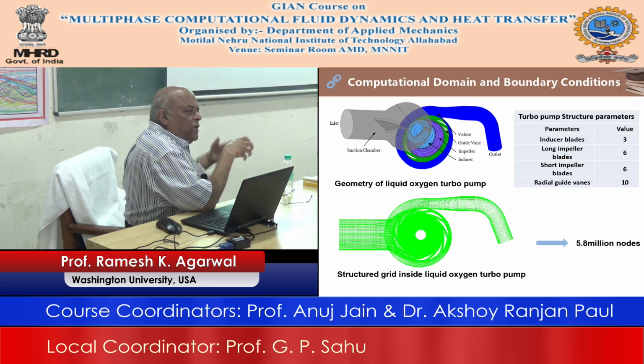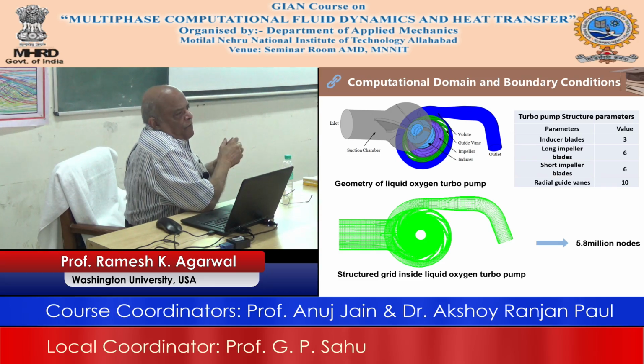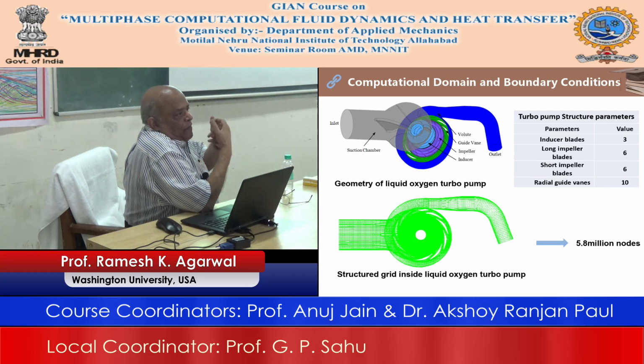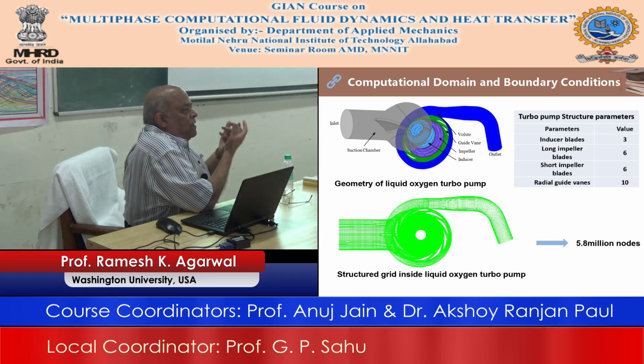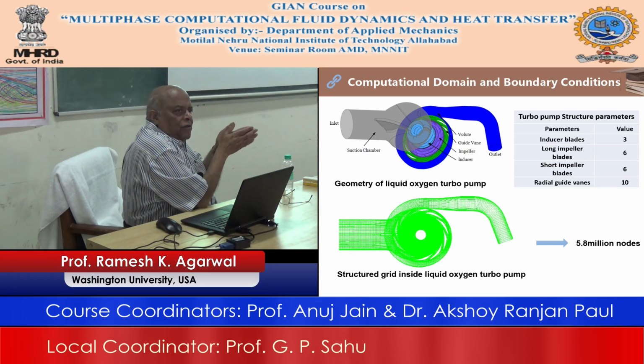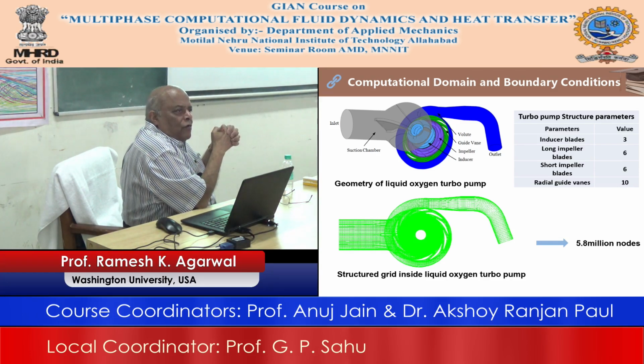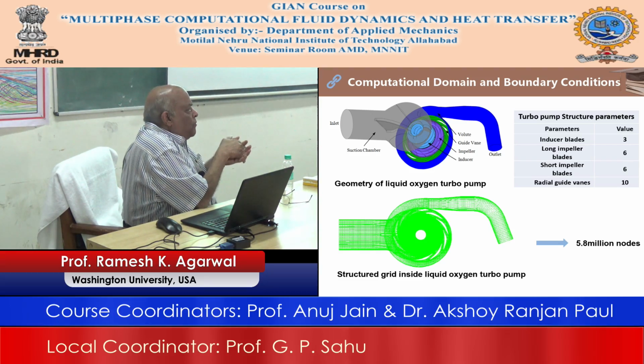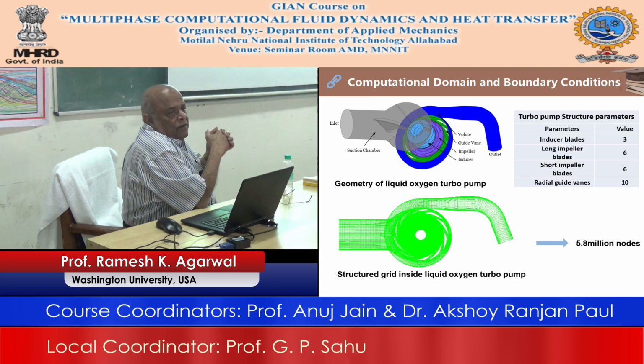All right. So which means that when you are using VOF, if the evaporation takes place and there is a liquid, then the alpha will change. If condensation takes place, alpha will change. So everything else is the same, except because of the effect of evaporation and condensation, because the temperature can make the liquid evaporate, or otherwise the temperature can take the vapor to condensate. You have to account for that effect when you are calculating the VOF,